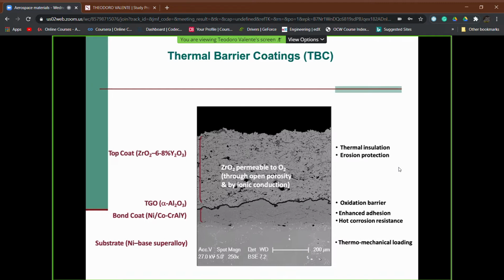And in between the zirconia and the nickel-based superalloy, another coating is used, which is named bond coat, and which is a metallic coating, usually a NiCrAlY composition, that is a metallic alloy made of nickel or nickel-cobalt, and then always chromium inside the composition, aluminum and yttria.